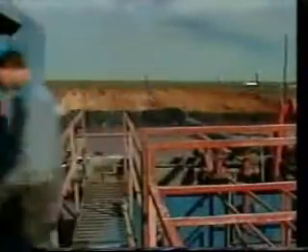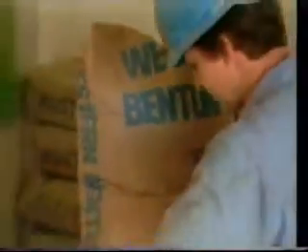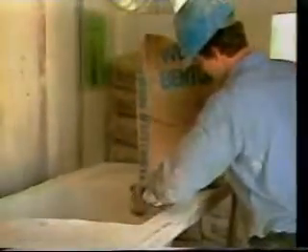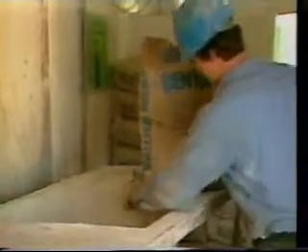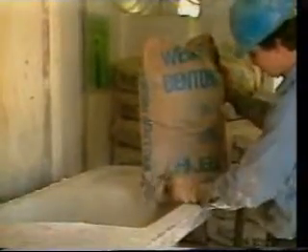Whatever type of bit is used, all bits perform their job with the help of the drilling fluid, which cools the cutting surfaces and circulates rock chips uphole from the bottom. Like the technology behind drill bits, drilling fluid technology has become increasingly sophisticated. In most cases, the circulating fluid utilized in a rotary drilling operation is a water-based mixture of clays, suspended solids, and chemical additives, appropriately called mud.